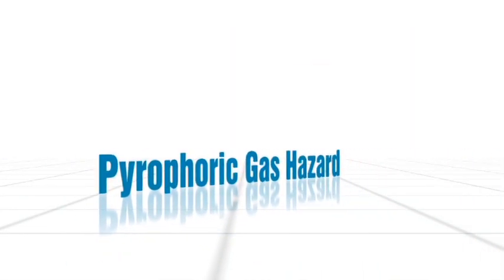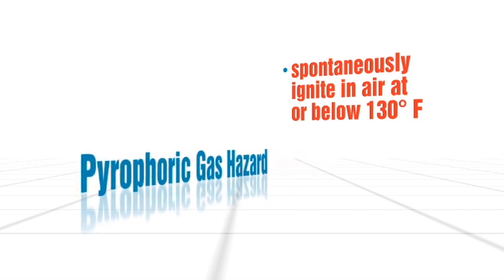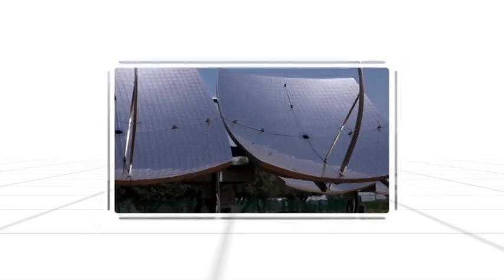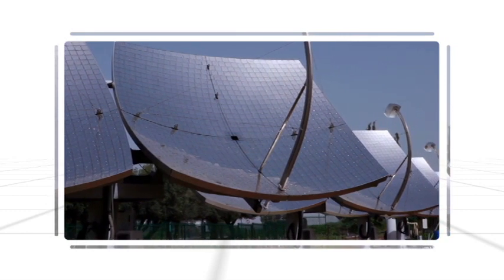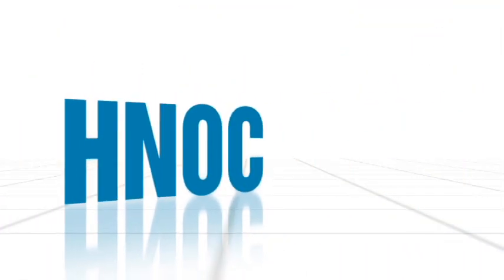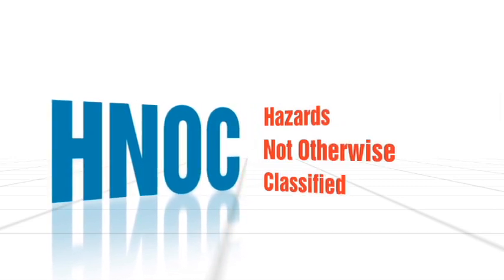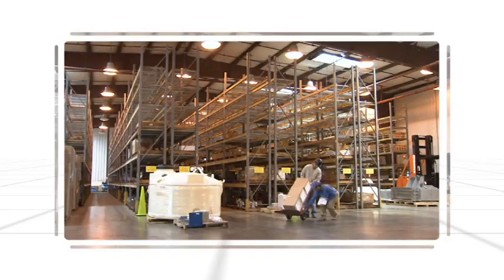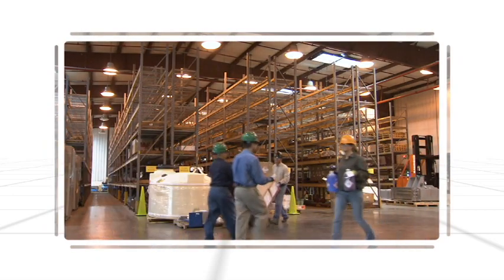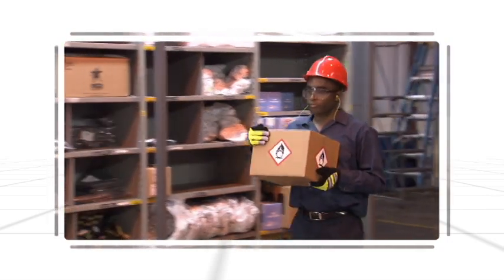A pyrophoric hazard is a gas that will spontaneously ignite in air at or below 130 degrees Fahrenheit. Silane is an example of a pyrophoric gas. Silane is used as a water repellent and in solar panel manufacturing. Finally, there are hazards that are HNOC, hazards not otherwise classified. A hazard that falls into this class is an adverse physical or health effect identified in the classification process that does not meet the criteria of other health or physical hazards, but either falls below the cutoff value or concentration limit of the hazard class or is under a GHS hazard category that has not been adopted by OSHA.